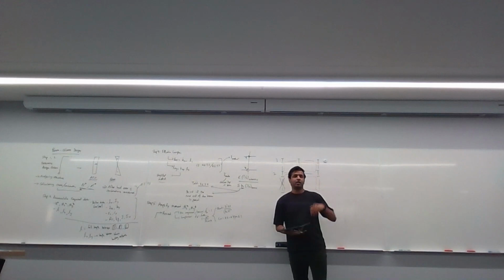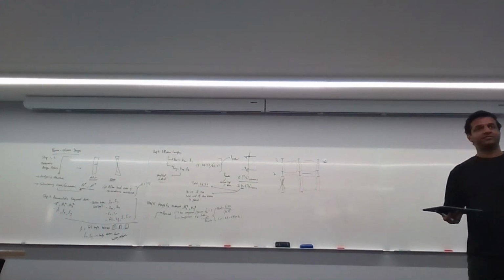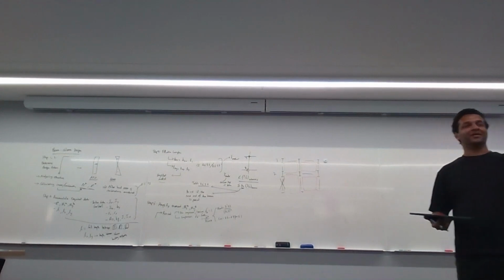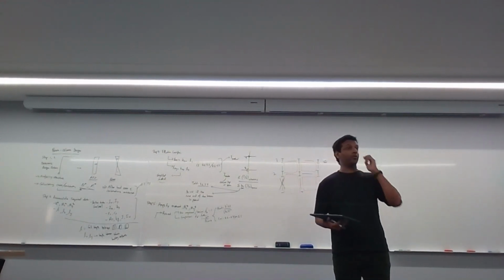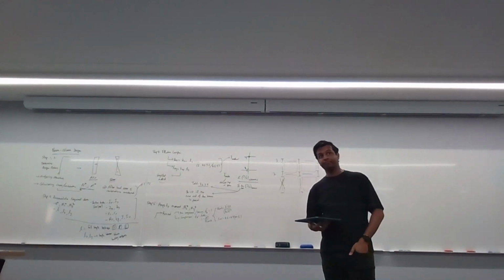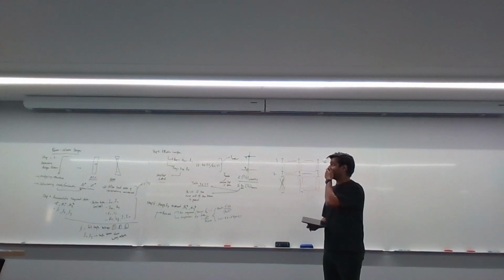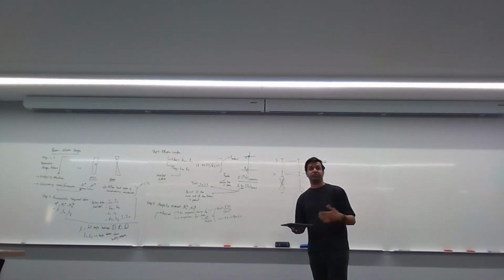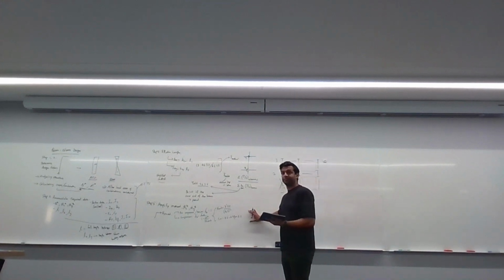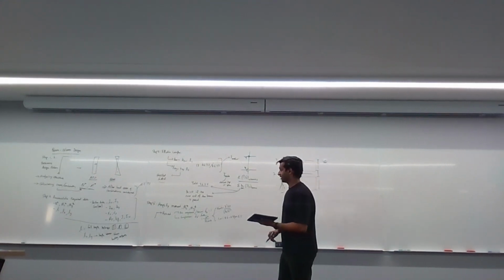Again, this is something that's already in the code, so if you can't see from the back, or you can't copy, don't worry about it. It's something that should already be in your notes. This is how you apply your moment amplification factor for a braced column. This was also covered sometime in week 4 or week 5, where you did compression design using the gamma method. This was part of it. You need your amplification factor.